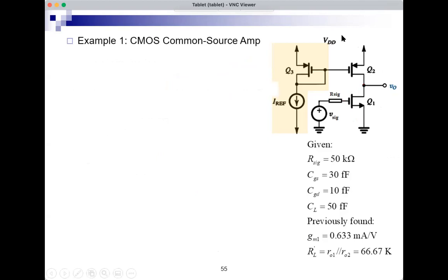Let's do now the OCTC. And in OCTC, I have my 3 capacitors. So again, this one, and now we don't apply Miller's theorem. So CGD stays and CL. And find the resistance seen by each of the three capacitors.